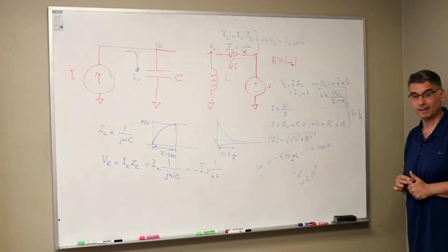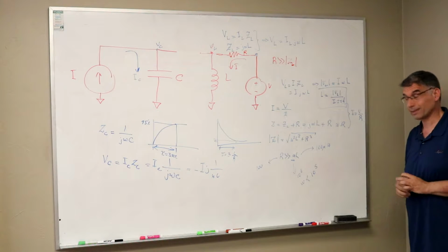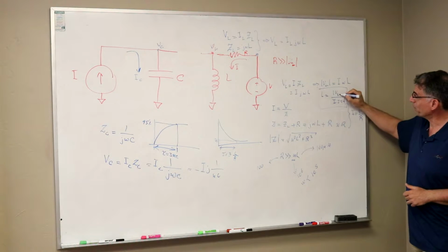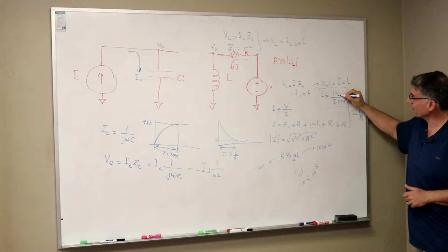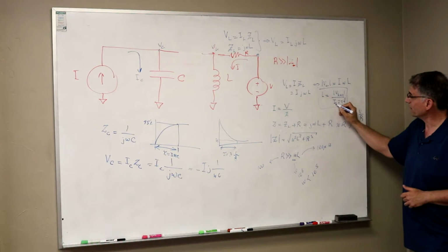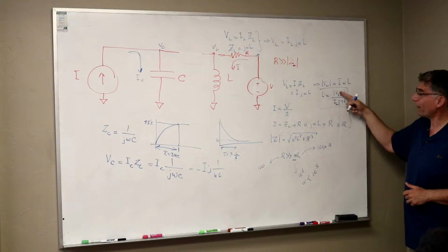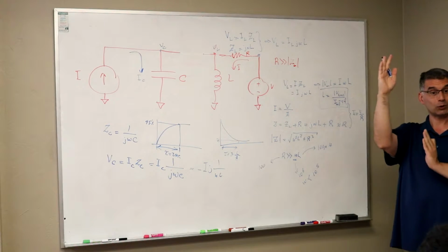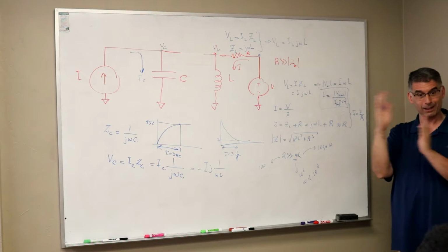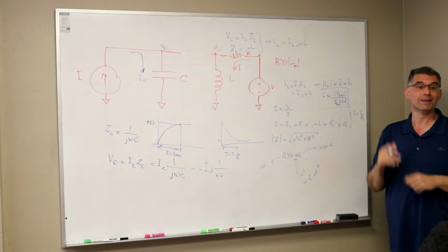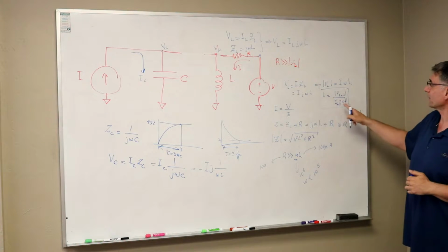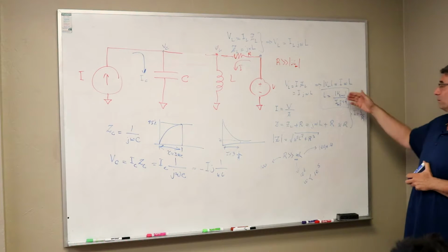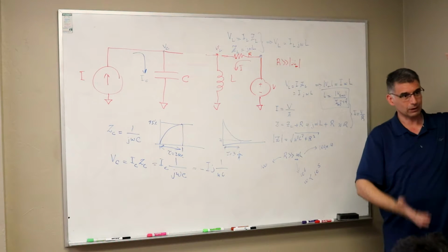The only trick was we were looking at the VL max because we were looking at the sinusoid, and then this I max, and realizing, because we know that these are 90 degrees out of phase, you're going to take those two values at the max points, even though on the scope they might not line up, and then you make this calculation, and you find what L is, right? And then we want to do it over several frequencies to get an average.